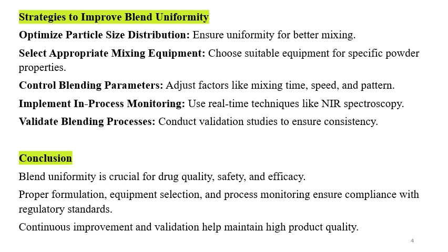Select appropriate mixing equipment. Select an appropriate blender. Then control blending parameters like blending time, mixing time, speed and pattern. Implement in-process monitoring like NIR spectroscopy.